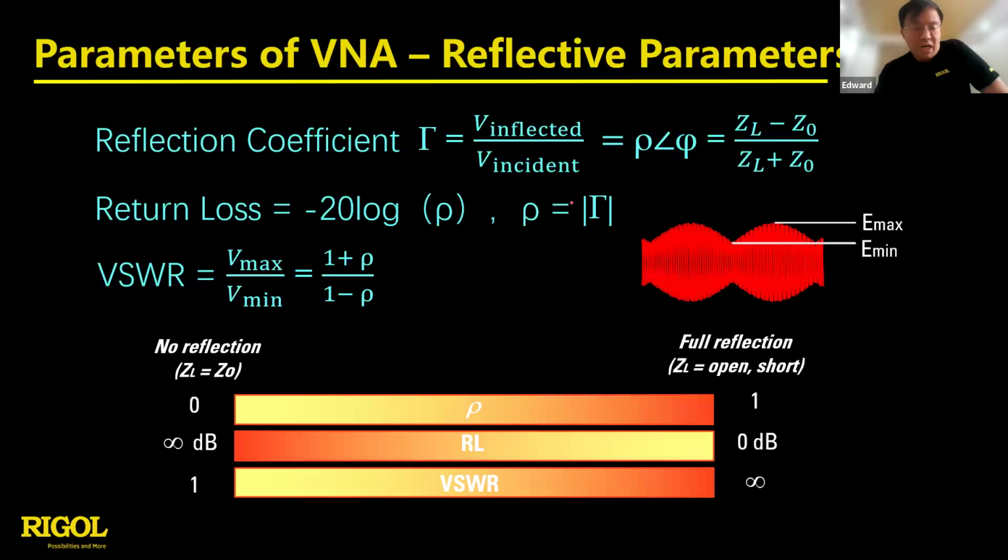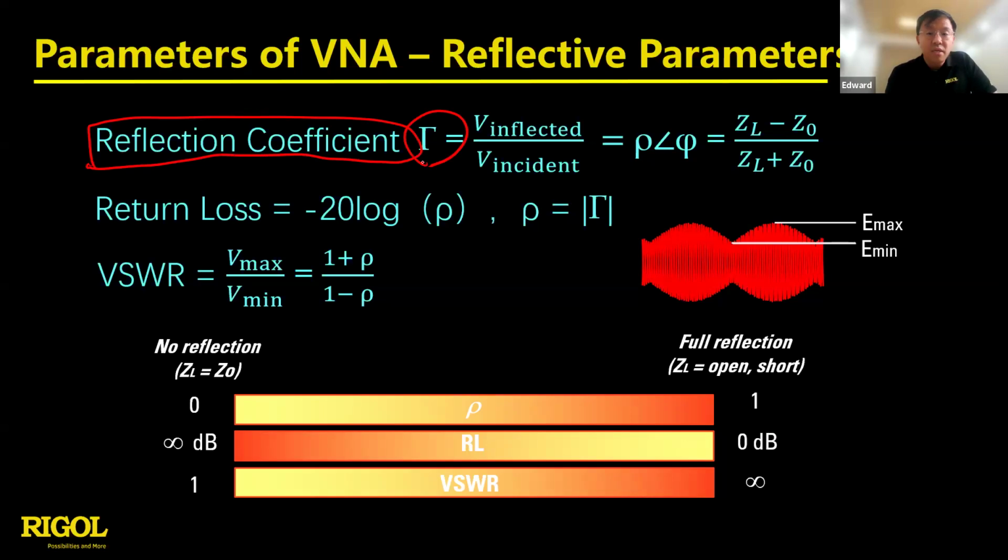So this is the electromagnetic theory about transmission lines. You can just see the formulas; I go through them simplified. Okay, so you don't need to remember this formula. We need to focus on this one, the reflection coefficient, gamma, right? So it is the reflected wave divided by the incident wave. Okay, this is a typo, sorry.